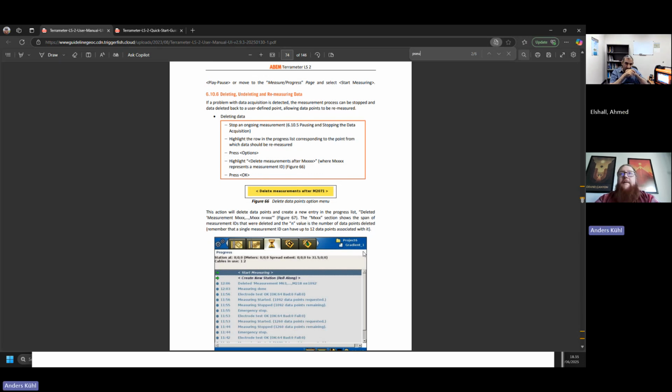Yes, gradient. You should try doing gradient and dipole first and see which resolves what you're looking at best, because dipole and gradient have slight differences in which types of structures they resolve. That comes from experience and the geology you're looking at.